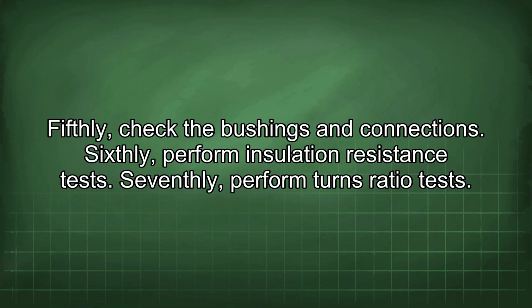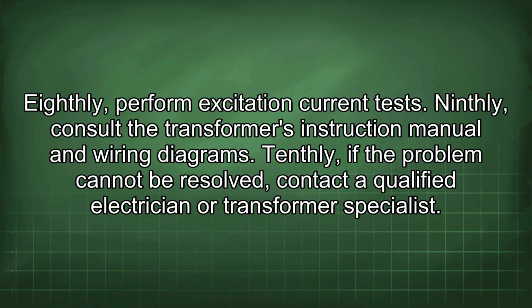Sixthly, perform insulation resistance tests. Seventhly, perform turns ratio tests. Eighthly, perform excitation current tests. Ninthly, consult the transformer's instruction manual and wiring diagrams. Tenthly, if the problem cannot be resolved, contact a qualified electrician or transformer specialist.